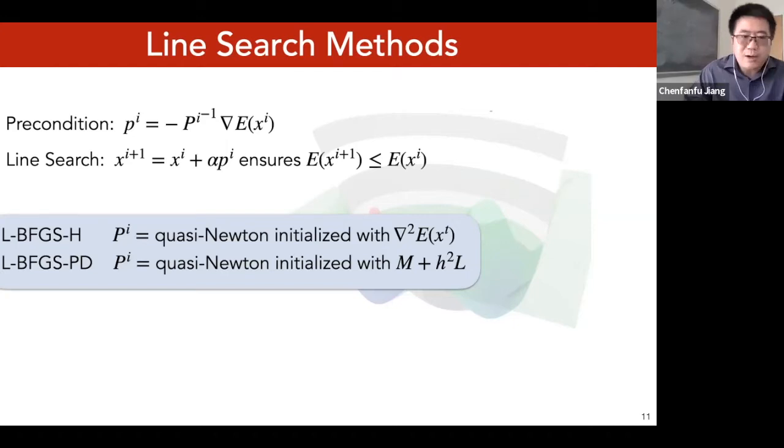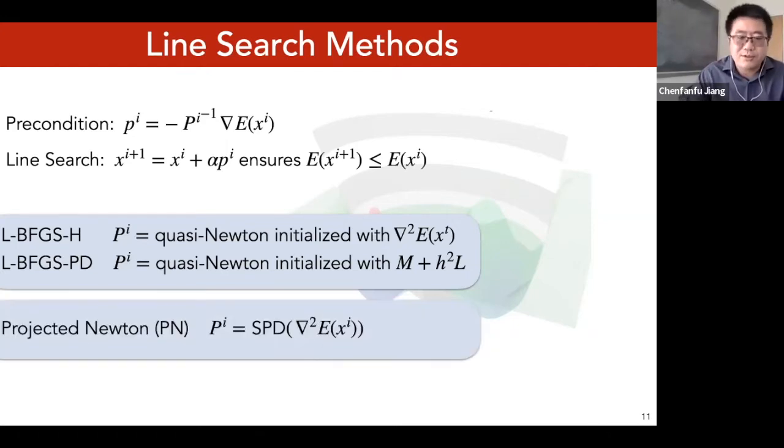A more accurate way is to just do the standard projected Newton's method, projecting the actual Hessian to SPD so that it guarantees a descent direction. By doing this, we get global convergence guarantees for Newton's method for optimization, even with a simple backtracking line search, where the only criterion is that your energy decreases. For finite element hyperelasticity, since the global Hessian matrix is assembled from element-wise stiffness matrices, all we need to do is the SPD projection on each local stiffness matrix by modifying its eigenvalues. It's very efficient in practice and can be parallelized over the elements.